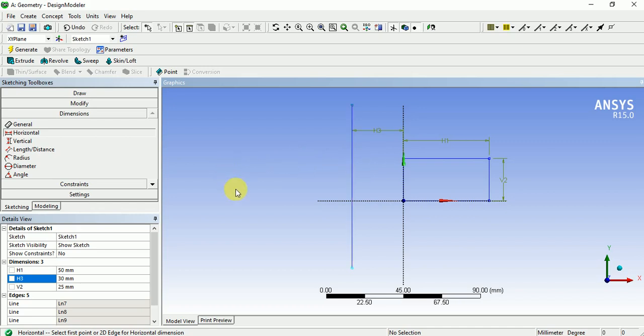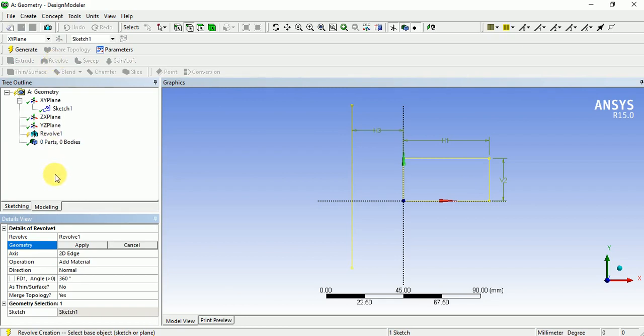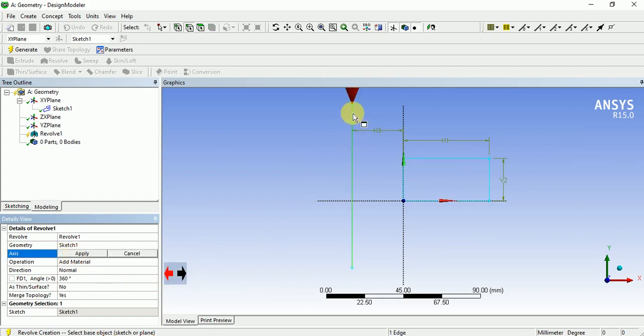Now I'm going to revolve the object through the entire axis. This is my feature. So take this revolve tool. Here the revolve tool is shown in the model tree, and this dialog box shows the revolve tool options. So this is my object, and sketch one is my feature, and this is my axis. It was selected automatically, and I can change the direction upward or downward. These arrow marks help to change the direction. So I have applied the direction.